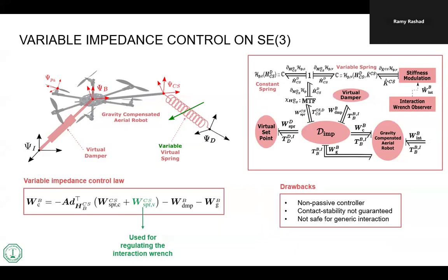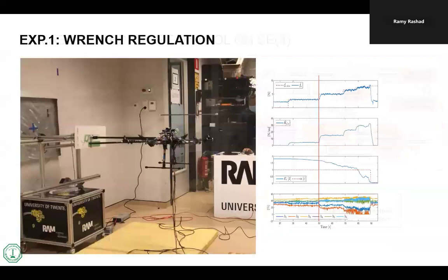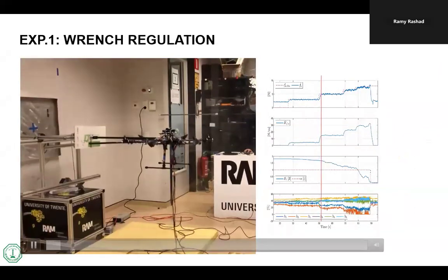That's the idea. So there is no force control alone and position control alone. Again, this is exactly what I'm saying. Don't think of it like this. It's not control of one and the other. It's controlling the behavior between both. You have to always think about what is the relation between the twist and the wrench that this controller is doing. This is the philosophy of the impedance controller.